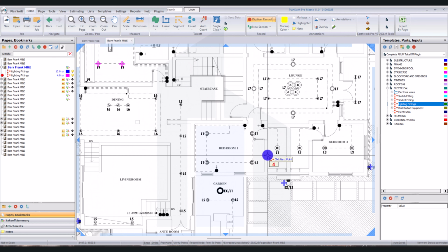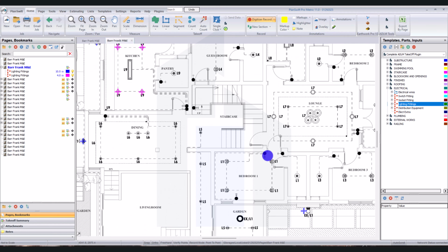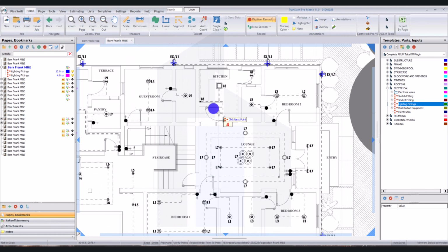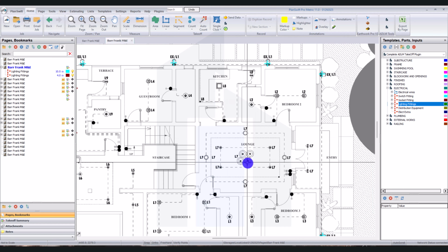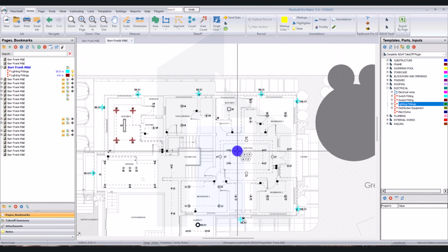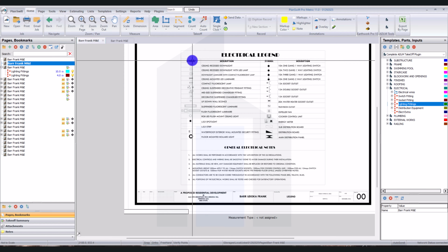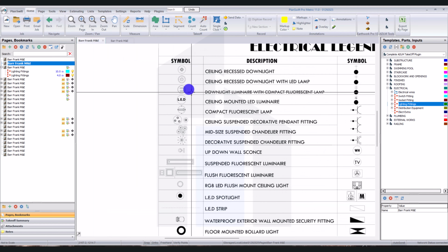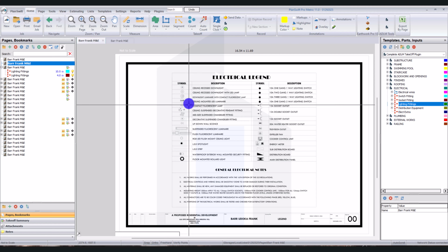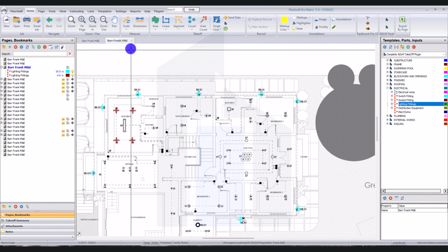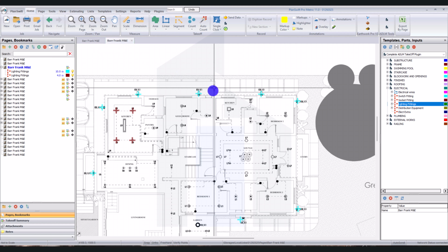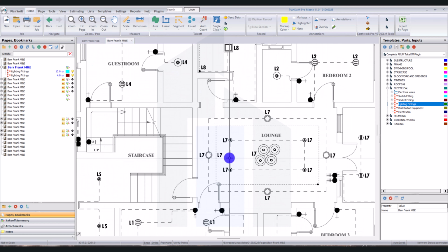So just take a glance throughout your entire model and you see, okay, once you've picked that, there's nothing more on that. This is a chandelier here. Okay, so based on the legend, this is a chandelier. So you just check the legend. So be familiar, electrical takeoff is basically easy. Once you can go through the legend and understand the legend like this, it's easy for you to pick the items. And you see the use of tabs or multiple screens makes your work very easy and your workflow faster.